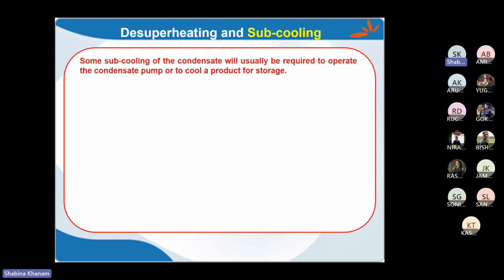Similarly, if I am having subcooling, you understand, that is to reduce the temperature of condensate. Okay, so little amount of subcooling of condensate will usually be required to operate the condensate pump or to cool product for storage. If you need to bring the condensate at storage temperature, that should be well below the condensation temperature. Okay, so that temperature at storage condition can be brought by subcooling only.